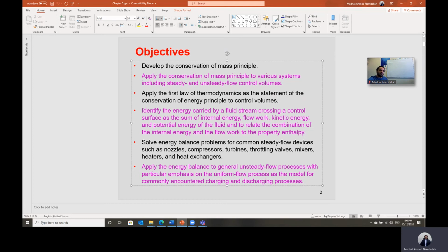As we have mass transfer, we have energy transfer by mass, and we have to identify this term. I think we have already identified this term in chapter 2. Energy transfer by mass equals the mechanical energy of the fluid, which is the part of the energy that can be converted to work directly without a device, plus the internal energy of the fluid, because this fluid has a temperature, so it should have internal energy.